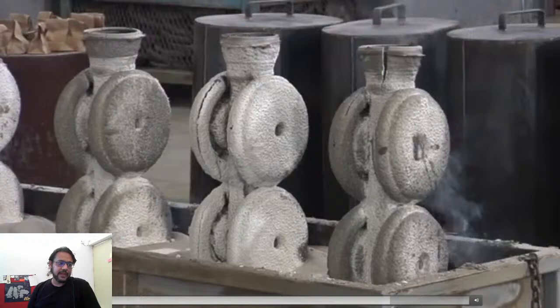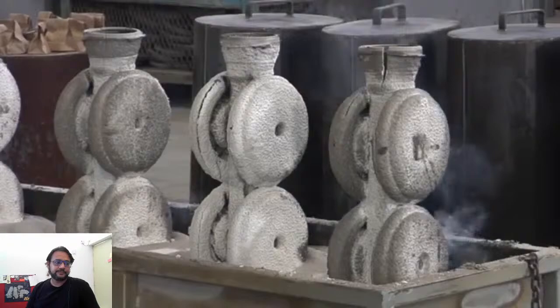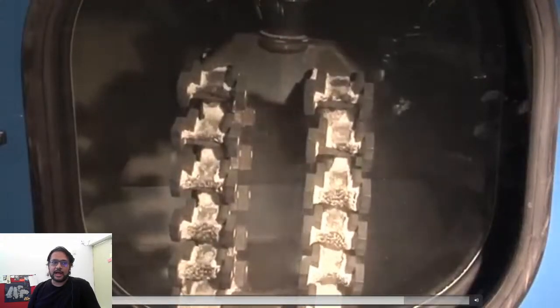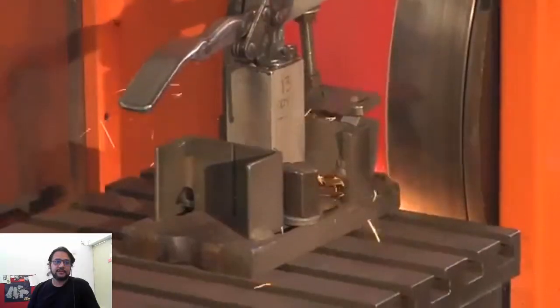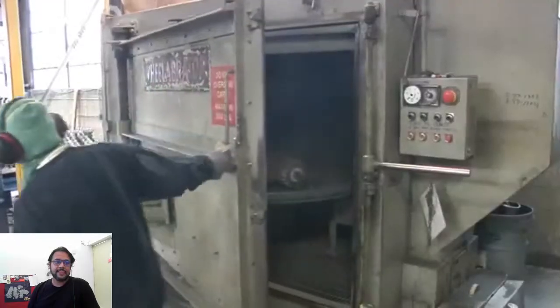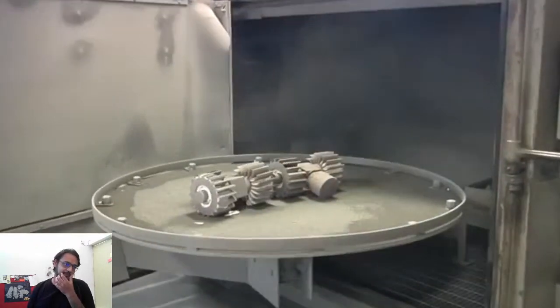The metal has now taken its solid form, and the ceramic shell is ready to be removed from the castings using a variety of cleaning methods, including blasting, vibration, or chemical cleaning. After you have poured in the material and it has cooled down, the process is straightforward. Break away the ceramic outer layer. The castings are cut from the sprue, and the ingate is removed by grinding. Finally, the individual castings are given a final cleaning to expose the smooth and detailed surface.